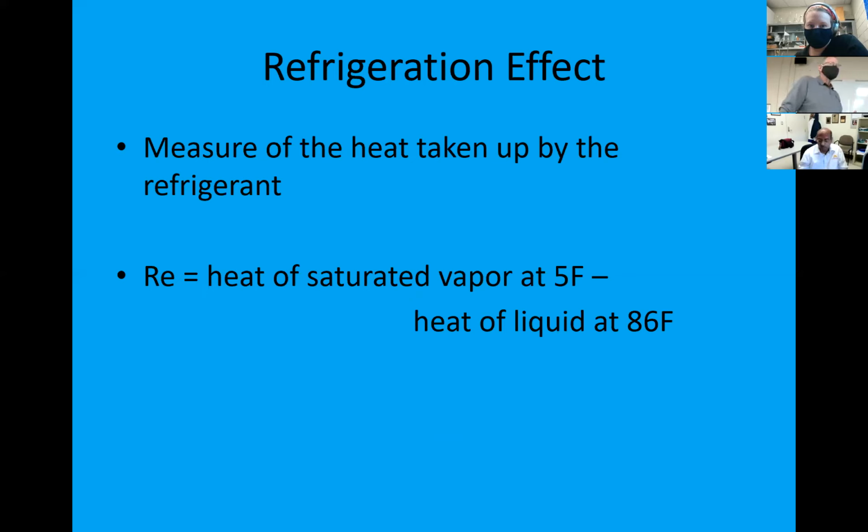The refrigeration people define refrigeration effect as the heat difference between saturated vapor at 5 degrees Fahrenheit and the heat of the liquid at 86 degrees Fahrenheit. Because remember that vapor, you've gone through a phase change, it is taking up a lot of heat.